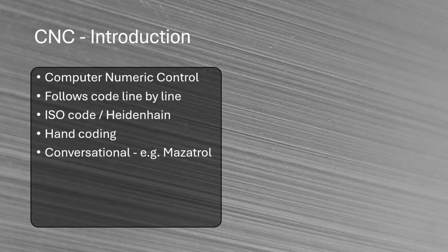The benefit of conversational is that it's really quick to change. Unlike ISO code, which can be fairly quick to create, it can get really cumbersome to change a program because you need to change everything. Whereas on conversational, you change one line and it changes everything for you instantly. Yeah, and that's why I say it in quotes, because it's like doing it in real time, basically. That's why it takes no time.